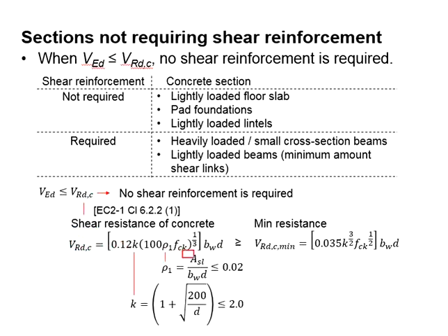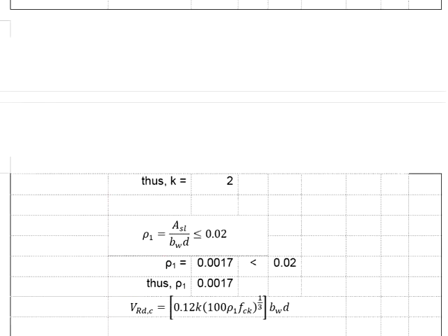Therefore, you may use the exact amount of reinforcement bar in the slab instead of the amount of reinforcement bar required. The b here represents 1000 mm, as the slab is designed on the basis of 1 meter unit width. As for the d here, it is equal to 115.